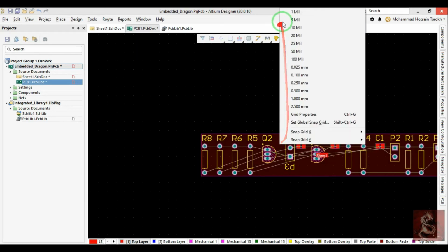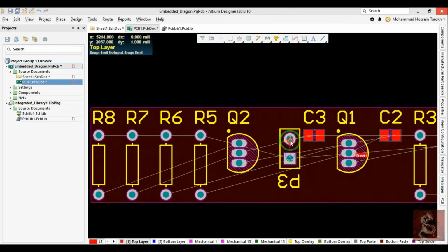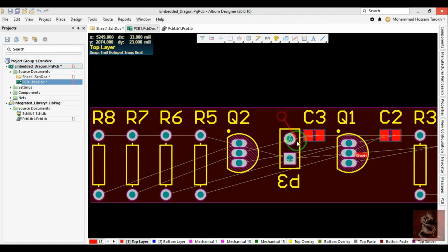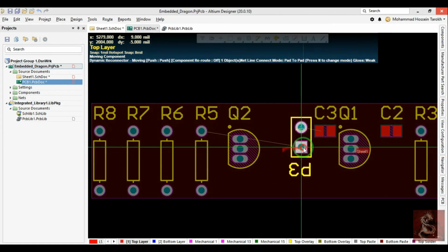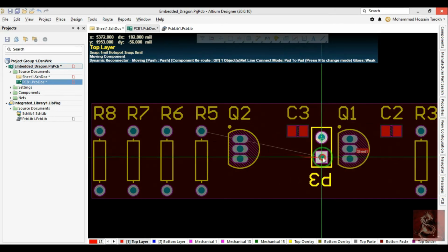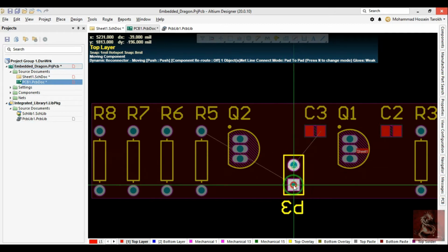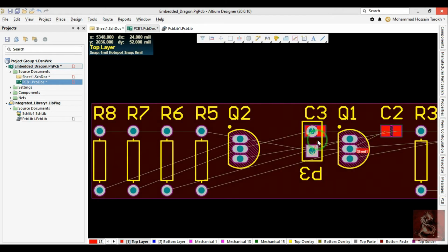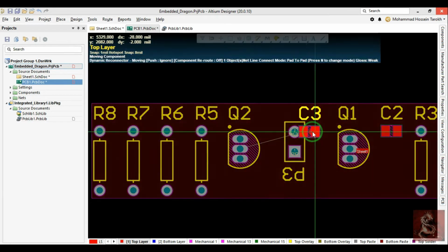But usually it's good to have the ability to move your components more, so that they can come very close to each other. It's also good that you can make a difference in how you move your components, and it's by pressing Ctrl R. With the original setting, without pressing, you can move the components and they can cross each other.